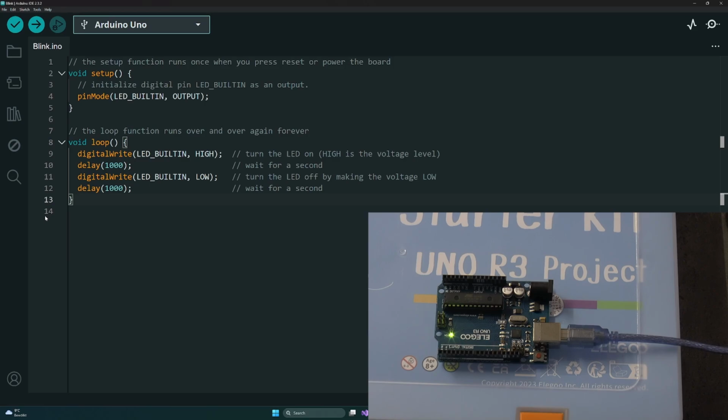But the Arduino might inject some other code into that to help keep up the Arduino's internal systems. That's possible. The Arduino can have control over the application flow by just providing you a setup and a loop function. In general, setup is called once at the beginning, which is kind of suggested because it's on the top, and then loop is called in a repetitive way.